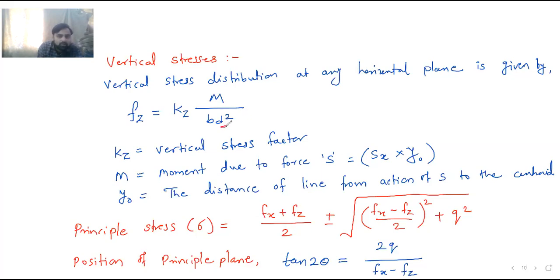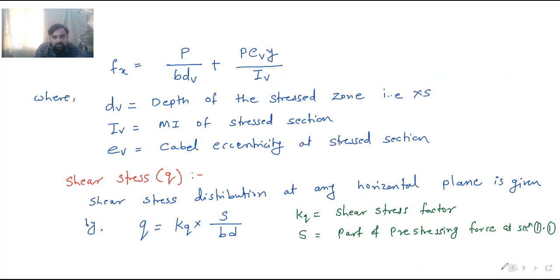So here we are going to consider the depth as it is. We are saying that you are mixing this formula with this. Here for the horizontal stresses, we take it in that way. dV is the depth for the horizontal stresses, and that too when the point where we are calculating that horizontal stress comes into that dispersion, then only our depth varies. Instead of d we go for dV.